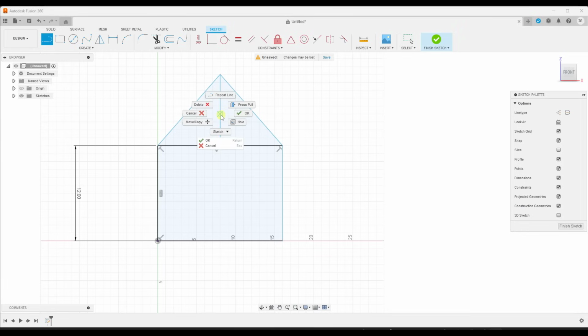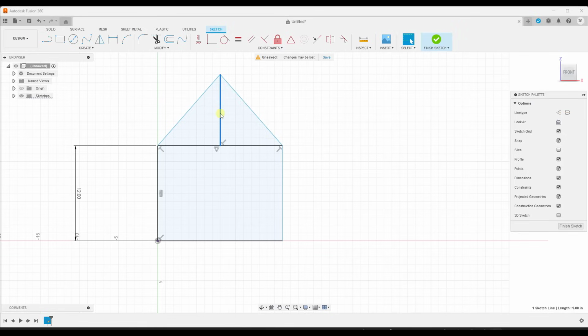And so what you can do is, first off, hit the escape key to deselect the tool that you currently have active. And what I want to do in this situation is come in here and select this edge, because I don't really need this edge. I just need this shape in here. So I can just single click on it and hit the delete key. Notice how when I hit the delete key, that deletes the edge that was in here, making this an uninterrupted shape.